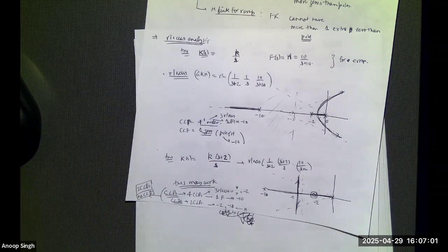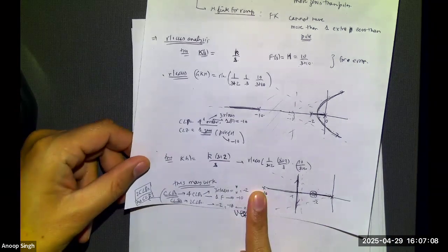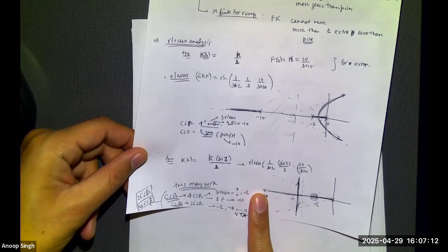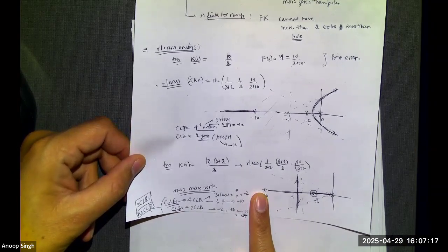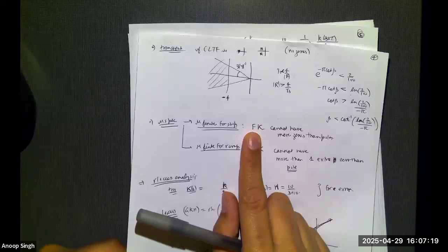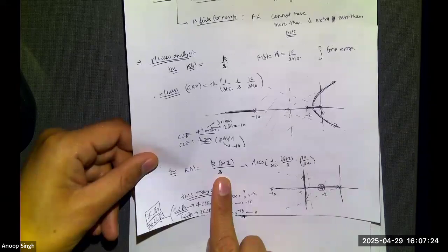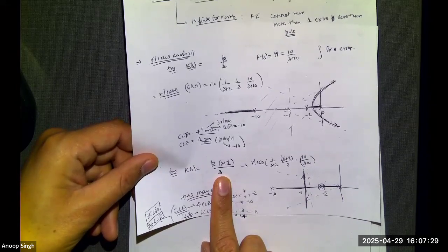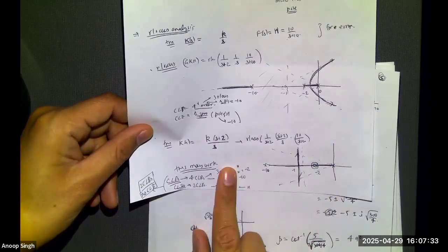Add a 0, cancel the -10. Okay, so I have a suggestion: add a 0. Is there going to be too many zeros now? If I add a 0, will it be okay if I add an extra 0 in there? Because the pre-filter already has a pole, so the controller can actually handle an extra zero compared to this. Oh, wait a minute. If I'm allowed to add an extra zero in the controller, then why don't we simply cancel this and make it a straight line?